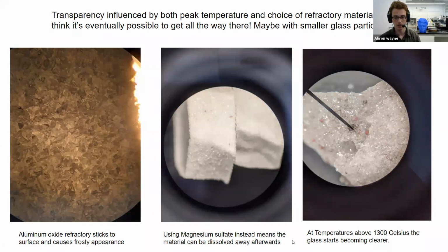sticking to the surface. And so one thing I wanted to try was using, instead of aluminum oxide, packing the material in magnesium sulfate, which is a salt. And then the idea is that I could sinter like usual, but then if they were stuck to the surface, I could wash them away afterwards. And this worked. Doesn't work at a very high temperature, but for certain applications, this is a good method.